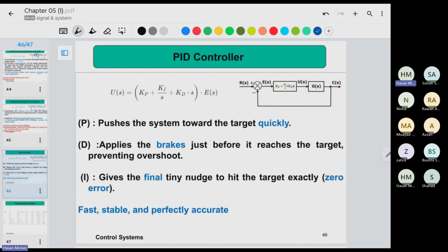So overall, these are the basic things. Combining all of these techniques is the controller we usually call PID, Proportional Integral Derivative. It might not require all of these things for any system, depending on the G(s). If the G(s) has internally some integration factor, maybe you don't need the integrator part, right?